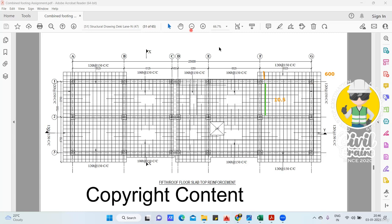Good. So maybe in future, if I get any cantilever slab, I'll do the BBS for that also separately. No issue. After this, we'll do the BBS for the crank bar. Now it was a cut reinforcement. Next, you put a bar something like this. It's called the crank bar system. So for this also, we are supposed to do the BBS. Procedure remains the same, but since we are giving a crank here, a different type of BBS has to be followed.